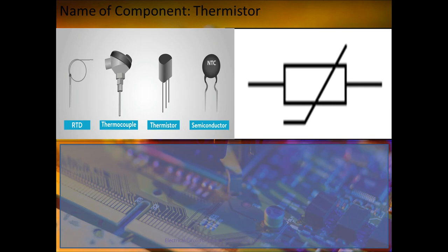Okay, our penultimate resistor is a thermistor. So again, just to re-emphasize, we have this rectangular shape to emphasize that it's a resistor of some sort, and then we have this kind of squared off tick going across it. Now, these are resistors where it's not an ohmic resistor, and it's technically not a variable resistor, but the value of the resistance does change, and it changes with temperature. Okay, so the resistance of these alters as the temperature changes.